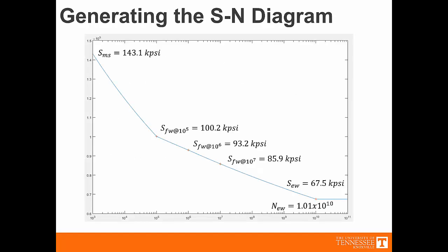So what we now know are the crossing points. We know up here, this is 60% of the ultimate tensile strength, and then moving down the list, these are the 3 that we calculated, and this one we were given. And what we need to find next is when these numbers of cycles will happen. I'll go through that in just a minute.